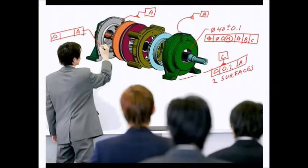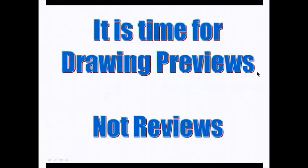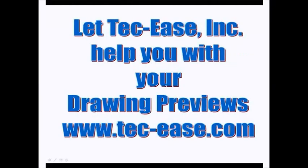The way you do this is to pull together the team and discuss how the parts are going to be assembled, what the critical features are, what kind of tolerances can actually be held, what the inspection methods will be, and then the answers to those questions are documented using datums and geometric tolerances. It's time for drawing previews at the model stage. Don't wait until the drawing's made and then have a review.